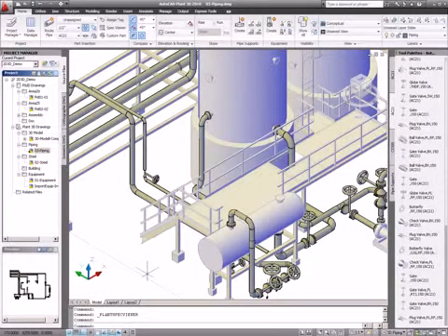Okay, remember the P&ID drawing we talked about. We created a line in the P&ID from the heat exchanger to the tank. The same thing we will do in 3D. As you will see, I will probably not touch this menu because I will pick every piece of information from the P&ID. I will show you three ways to do the piping. I will show you from the P&ID, and in the end I will also show you how to create a new pipe in the 3D. And then we will do something called a validation. We will validate between the P&ID and the 3D. I will come back to that a little later.